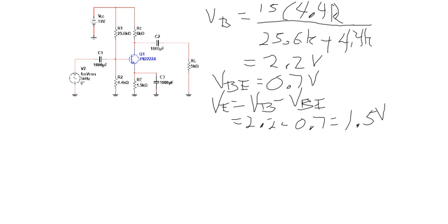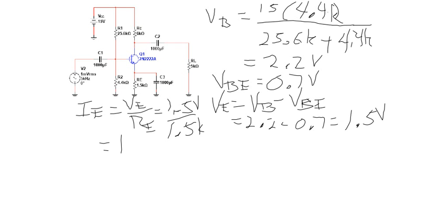So IE is going to be VE over RE, 1.5 volts over 1.5K ohms, or 1 milliamp.